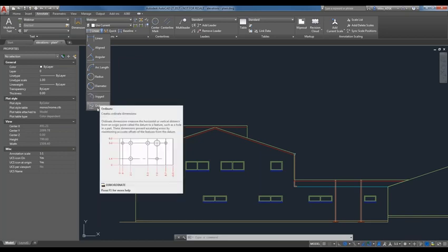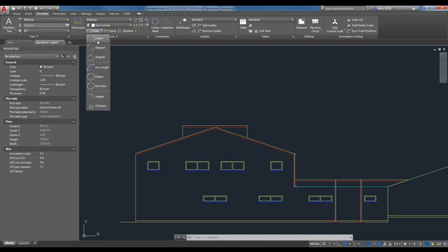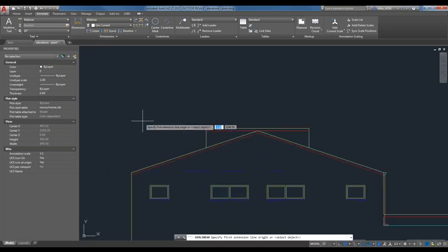You also have the ordinate option down here. The ordinate option, if you look at the picture in there, basically what ends up happening is, if you're showing dimensions, say I want a circle maybe 1 foot from my start point, and then if you end up having a mistake at each interval, you'll end up with something super off at the end of your design. So you can measure the distance from the origin as it's shown and explained in there. But yeah, there's a bunch of different ways that you can place dimensions in here.